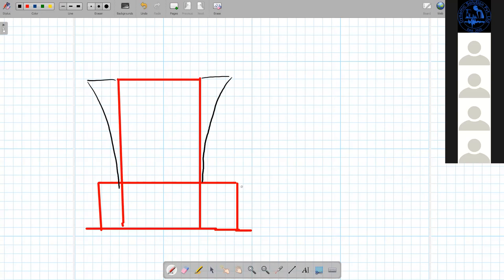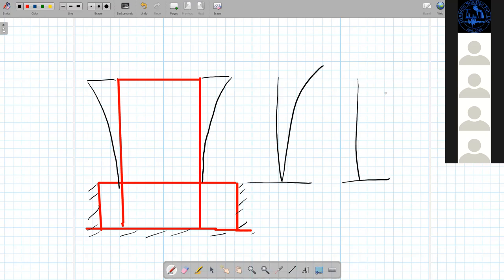Bottom portion is moving along with the ground. It is not vibrating with respect to the ground. So when you do the modal analysis, you will get different modes in this height. The bottom portion will not be involved in those modes. Its displacement will be more or less zero. And when you calculate seismic mass, your mass participation will also come out very low. This mass will not participate there.